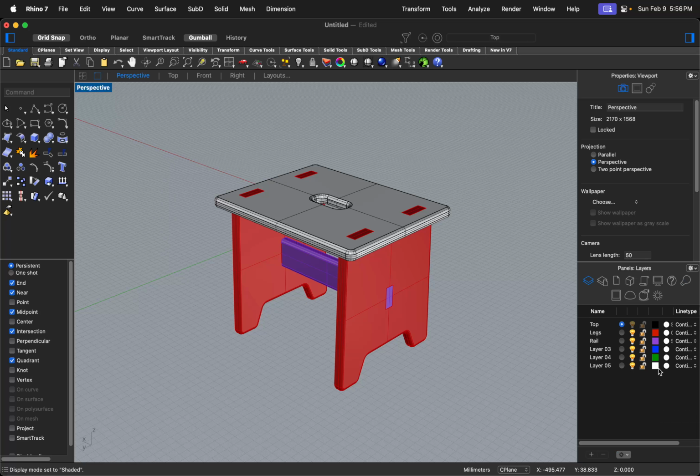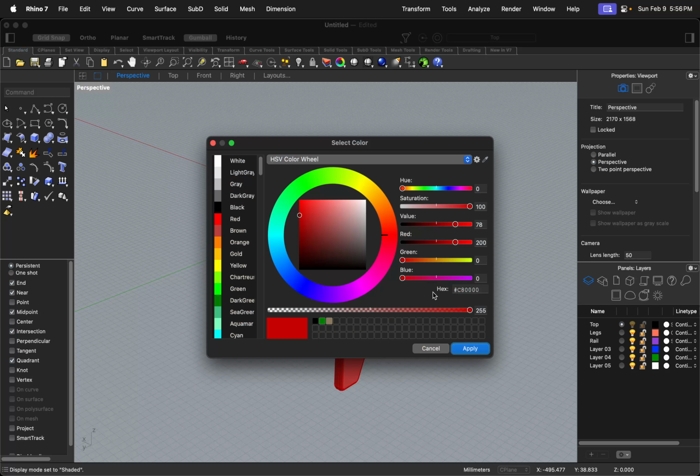And I will change all the layer color to be black, easier for me to manage later on the outcome. Otherwise, if you use all fancy color, your drawing will also look very fancy, which is what we don't want. Okay, look at the model. I will then set the view and set my symmetric. Okay, that looks alright. I'm going to choose the entire kitchen stool, go to dimension, make 2D drawing,